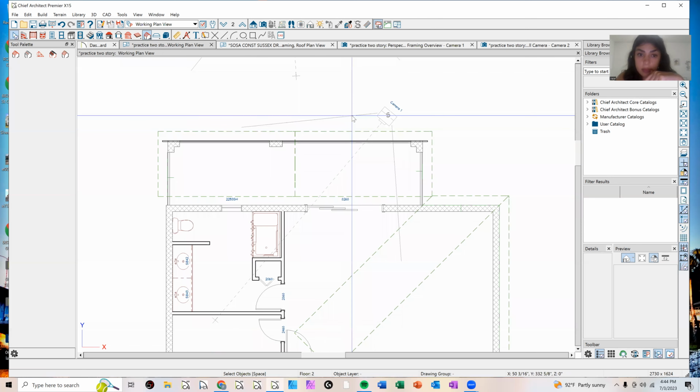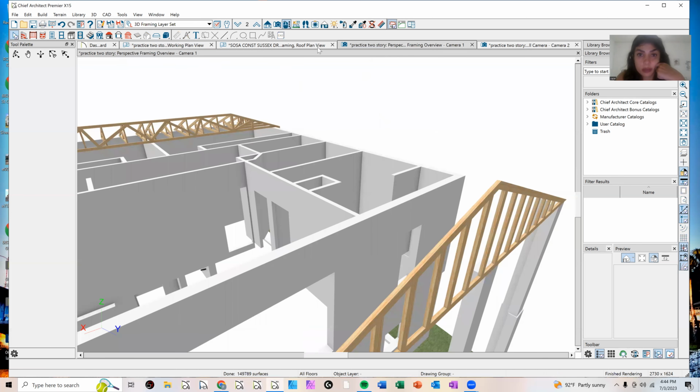The end gable has so many things going up and down because you need that because you're putting material on the outside. You're either going to be putting stucco over it, right? So you need to have a lot of pieces of wood so you can nail all that stuff in. The inside gables are only for support, so they run like this. I'll show you how the legs go on those.